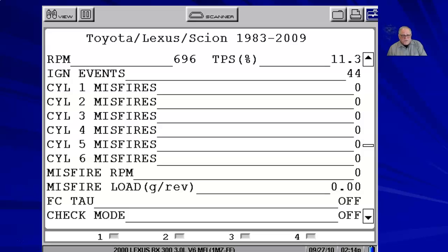What happened is when the misfire in cylinder 2 happened, it created an imbalance that fooled the computer to think cylinder 5 was misfiring. Look at your misfire. Look at your one that is the highest number. Concentrate your repair on that one. When you get that fixed, chances are you'll fix all the other misfires too. If you didn't, then you have to go on through and do it.